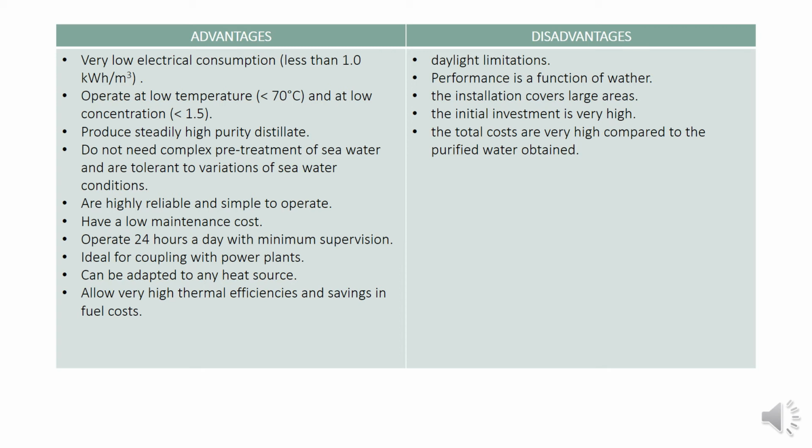Advantages: very low electrical consumption, less than 1 kilowatt hour per cubic meter; operate at low temperature, less than 70 degrees Celsius, and a low concentration, less than 1.5. Produce steadily high purity distillate. Do not need complex pre-treatment of seawater and are tolerant to variations of seawater conditions.